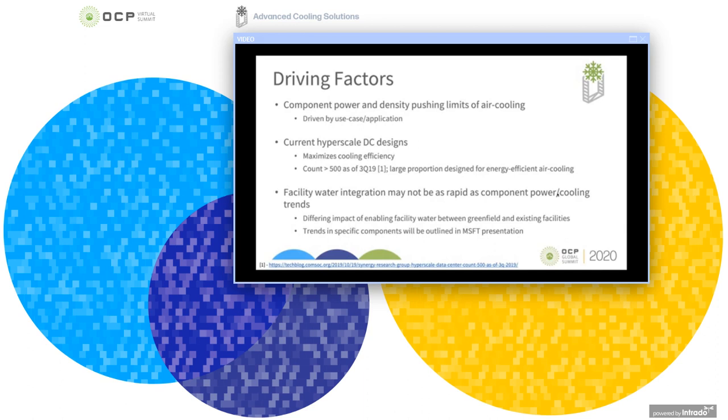But in light of the fact that most of current hyperscale DC designs have been optimized to be most efficient and cost-effective using air cooling, we have to be cognizant that not all applications might require those higher flux chips. We might end up with mixed low flux and high flux chips throughout the facility. So we need to make sensible TCO-driven decisions. Do we need water throughout the DC or locally where needed, or what we will be showing you here today, which is the use of air assist water cooling.